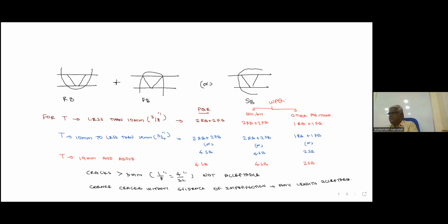These are important. Now, what is the relation between hardness and PWHT? You can see sometimes after the PWHT chart, they will mention the hardness also. There is a column. Hardness is one of the ways to confirm whether the PWHT is done properly. If PWHT is done correctly, hardness value should come down. A high hardness value shows that PWHT is not done properly.